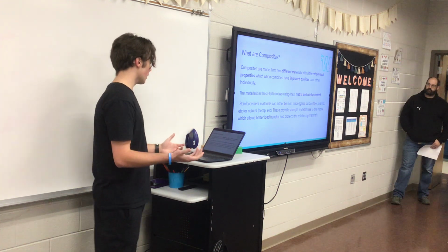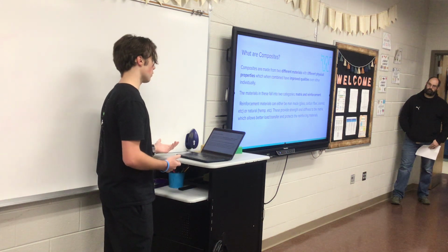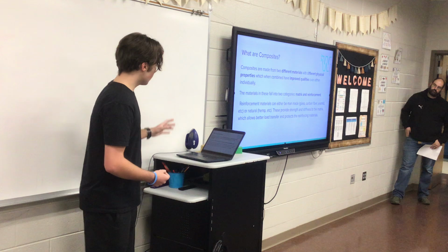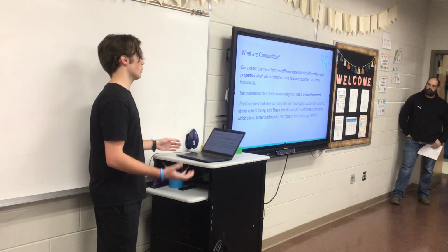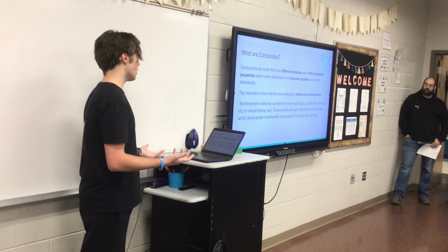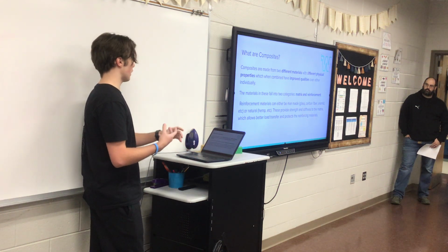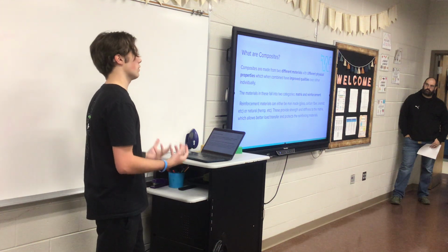Those are man-made, but you can also use natural fibers as a reinforcement material, like hemp. These provide strength and stiffness to your matrix, which in a lot of cases tends to be epoxy resin, though it can be other resins. What the matrix does is allow better load transfer and protect the reinforcement materials.